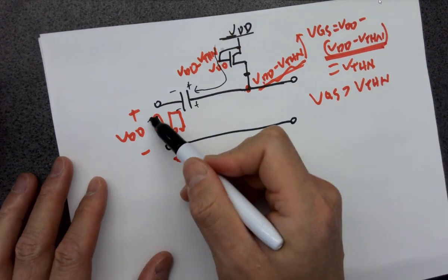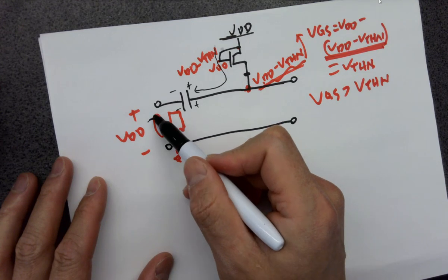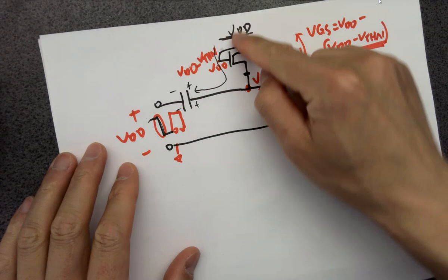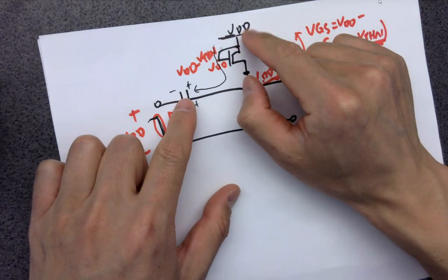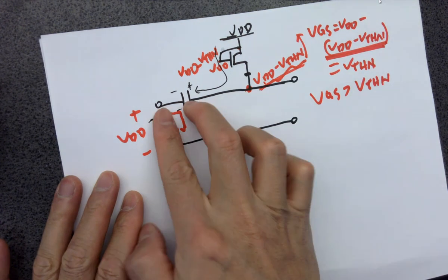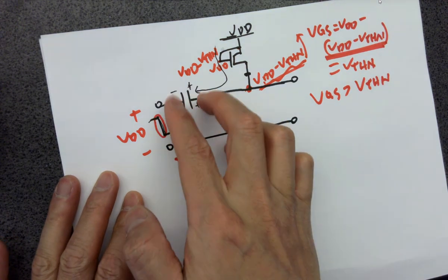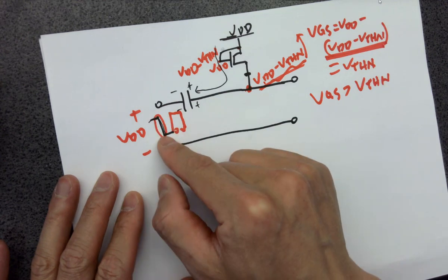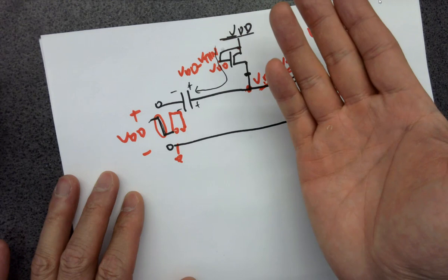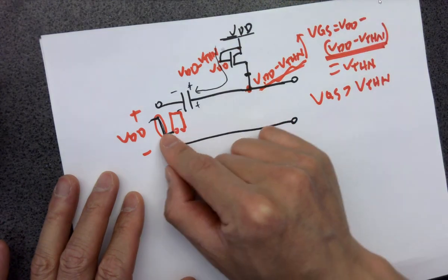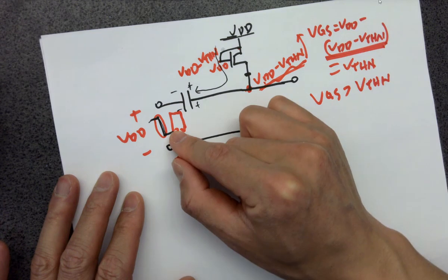So whenever it's 0 at the falling edge, at the ramp, it's pulling. It's discharging from the voltage source and dumping charges to this point, and then eventually forms a VDD minus VTHN voltage across the capacitor at the falling edge. After the falling edge, it maintains a 0, which is not doing anything because the DC voltage is not changing. There's no current. And then right after that 0 volts, it starts rising again.